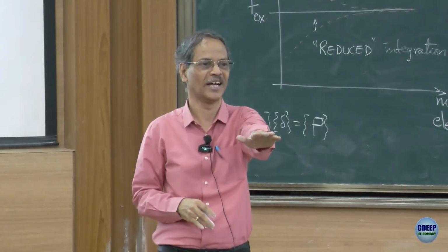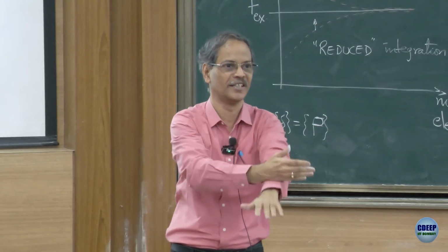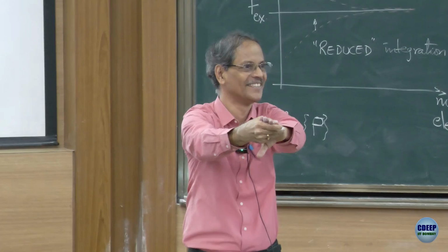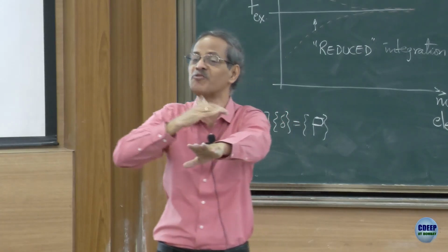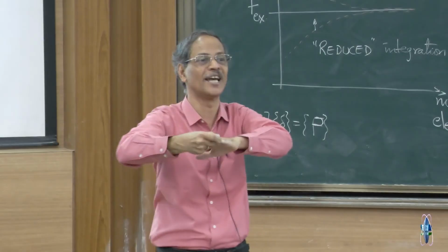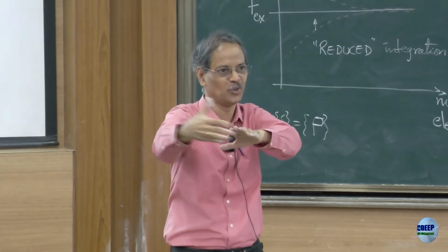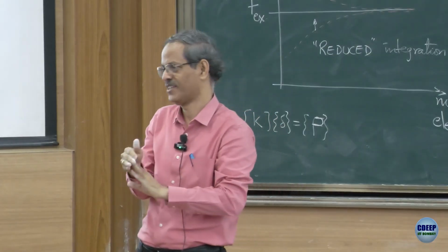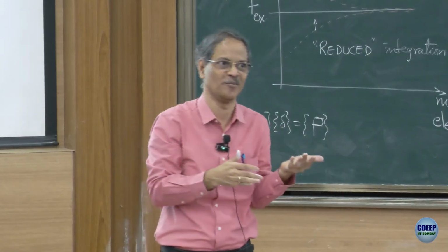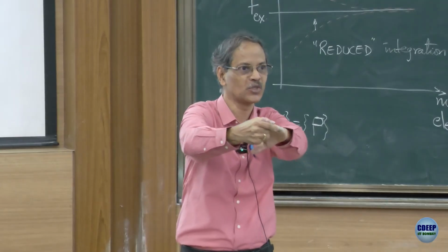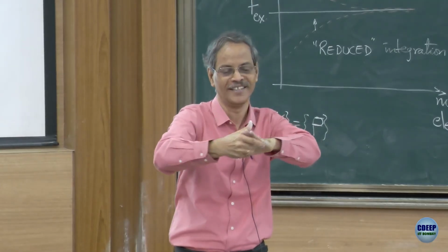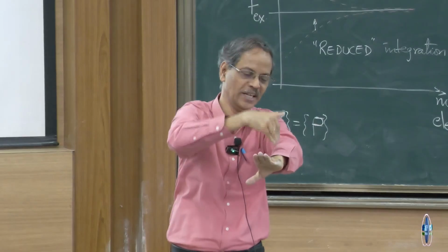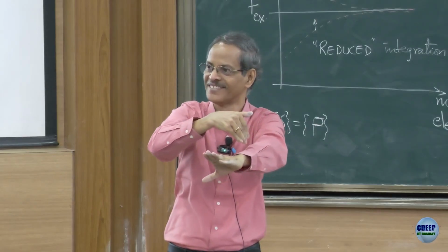Just pull out your hand, somebody applies a force, then the hand will deflect. But ask another friend to pull this hand, then this will be a little stiffer because there is a tensile force. Contrary, if you push it, compressive force, then this will become less stiff. So, more deflection will be there. So, there will be a force interaction between the in-plane force, stiffening force, and the out-of-plane load.